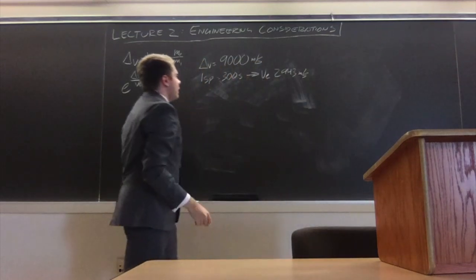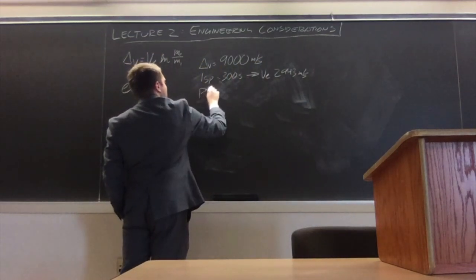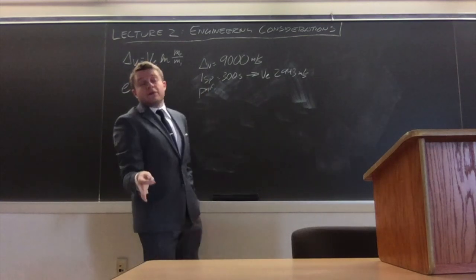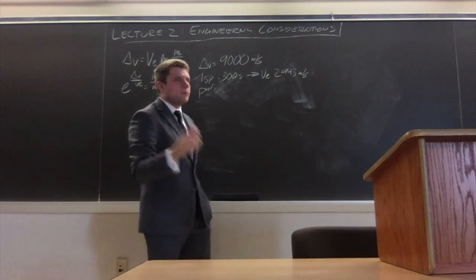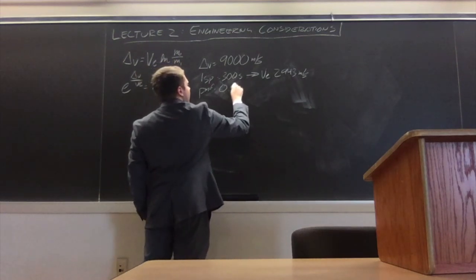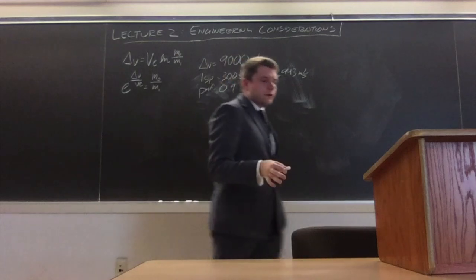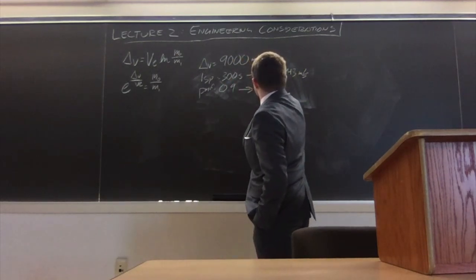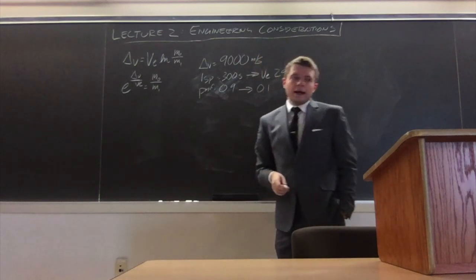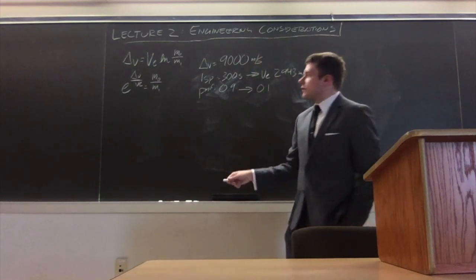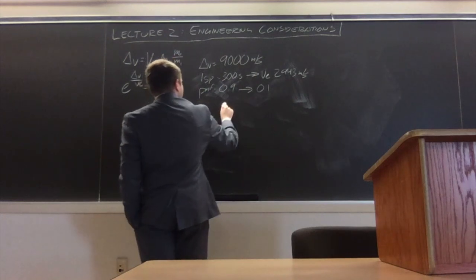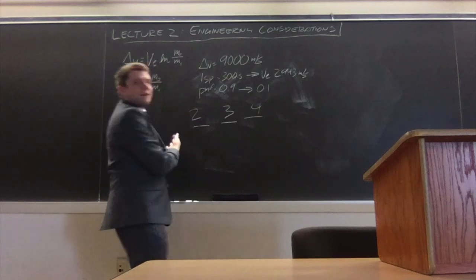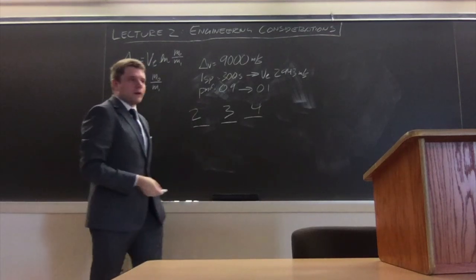And then a propellant mass fraction, which is a little bit higher than what we're actually going to be expecting in this rocket, but I use this because it's just a nice round number and it's easy for me to play with in a notebook. 0.9. And with those considerations in mind, we can of course derive the inert mass fraction, which is 0.1, because it has to add up to 100%. And I ran through 3 different scenarios with a 2-stage rocket, a 3-stage rocket, and a 4-stage rocket. Obviously, 1 stage is kind of impossible to do, so we won't really worry about that.